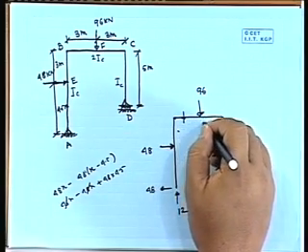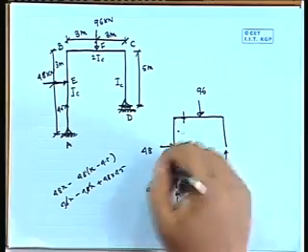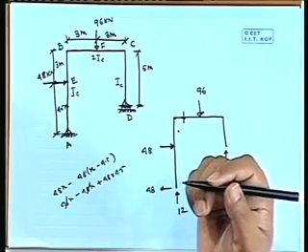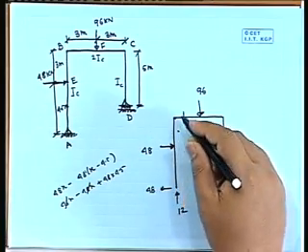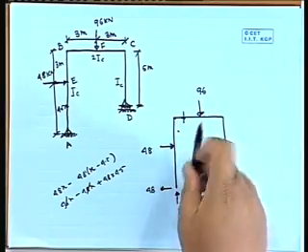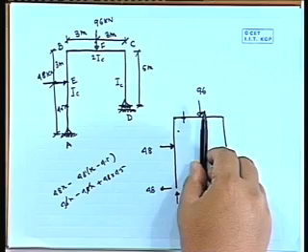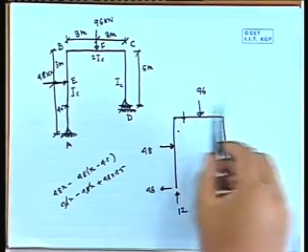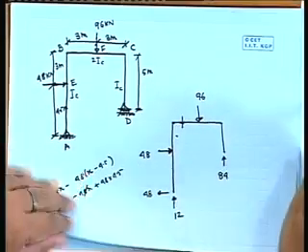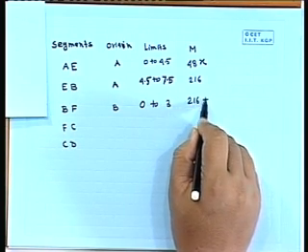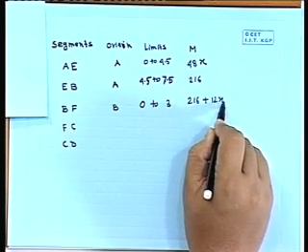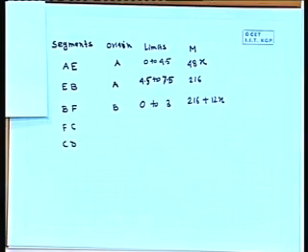So at any station, if you take these two horizontal forces, they will make 216 moment, plus this vertical force 12 will give a moment here. So 12 into x will be the moment value. So moment here it will be 216 plus 12x, right?